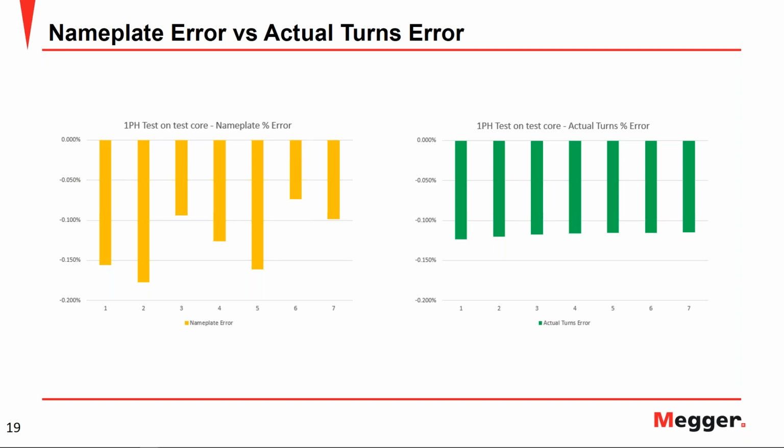But when you do have to run the whole run of positions in the tap changer, you do as many tests as positions you have in the tap changer. You have the voltage ratings for those positions in the nameplate of the transformer. So neither the software nor the instrument itself is doing any compensation. You're actually measuring the ratio for all the different positions, and then with each result you compare to the corresponding ratio that you calculate from the nameplate.